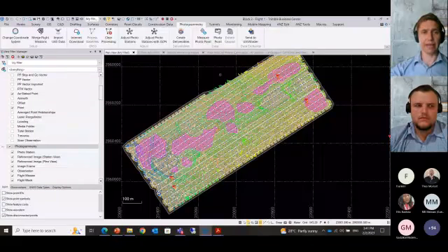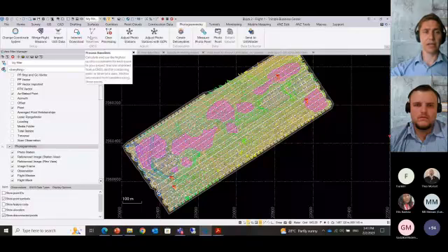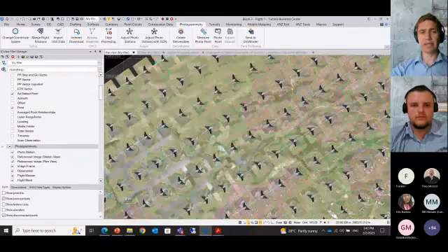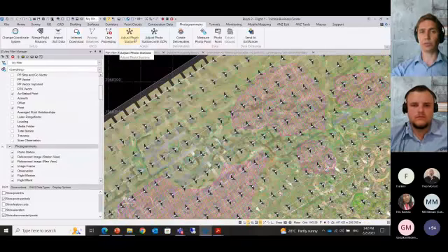of your UAV data. So what you need to do first is to process your baseline. So you basically merge your flight missions. Then you move over, you process your baselines, then you will ultimately get this, okay? And then next up is to start with your adjustments.